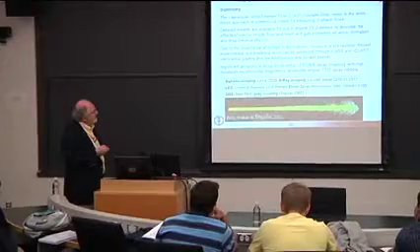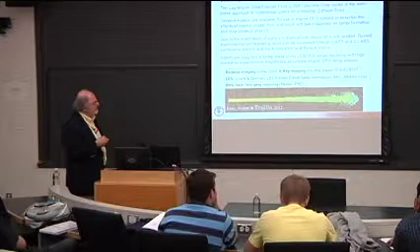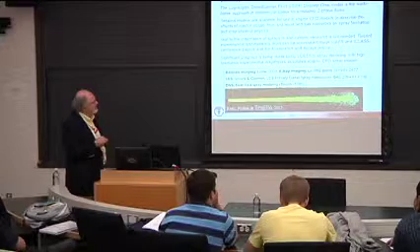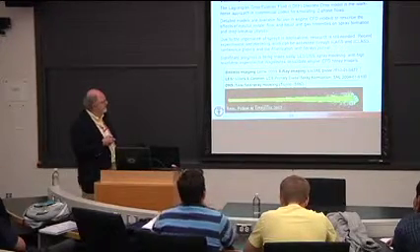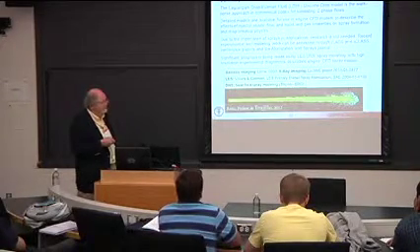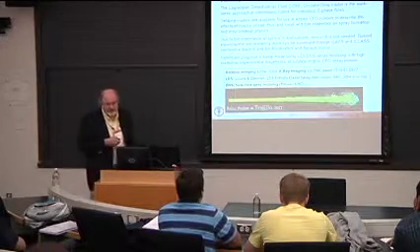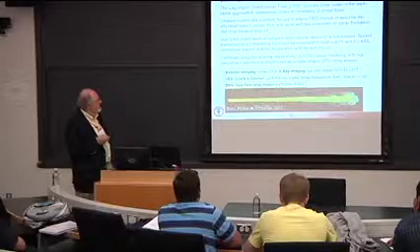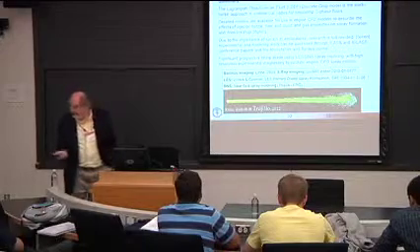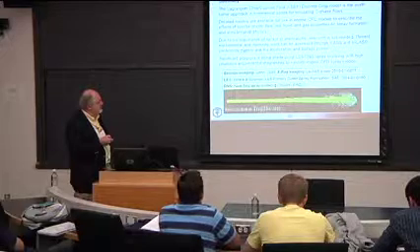So some of the models are quite detailed now. They're available for engine CFD codes. They provide a description of what happens in the nozzle flows, the effect of the liquid and gas properties on spray formation, and the drop breakup physics, as we've discussed. But due to the importance of sprays, a lot of research is still needed. And in fact, if you attend meetings such as ILASS, the Atomization and Sprays meetings, or ICLASS, lots of papers in atomization and sprays are dealing with these very topics: how to improve the collision models, how to improve breakup models, and so on. So there's a lot of progress being made.